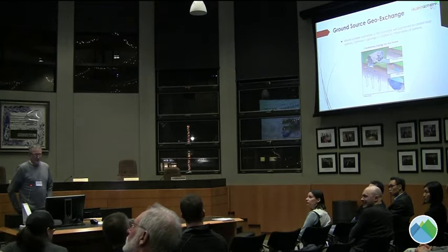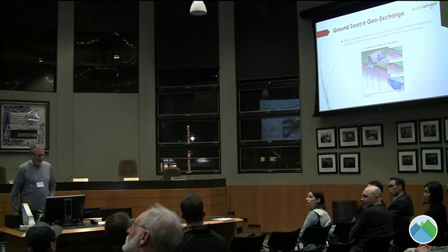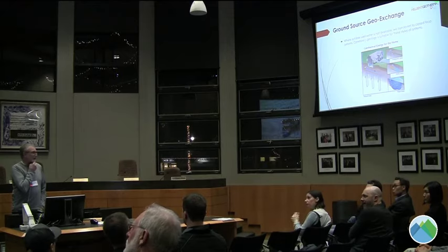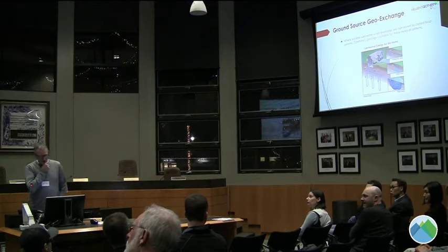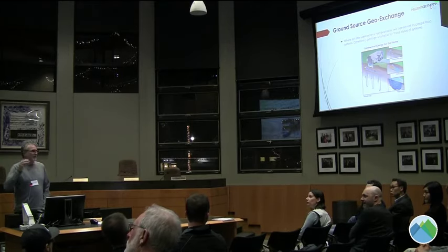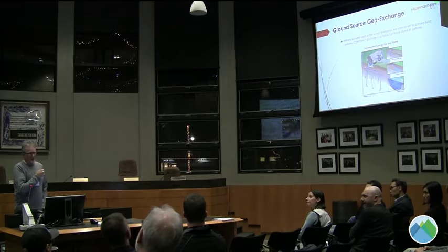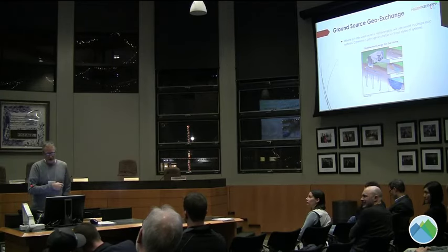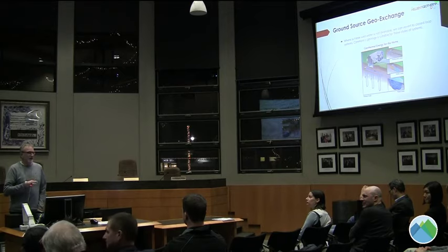If you don't have access to the aquifer here, and you're up on the hillside, you're going to be faced with having to drill a closed-loop system. So basically, it'll be drilling multiple boreholes. The average home would probably need 4 or 5 200-foot boreholes. So even though it'll work great, it's going to be an additional cost to drill those extra boreholes.